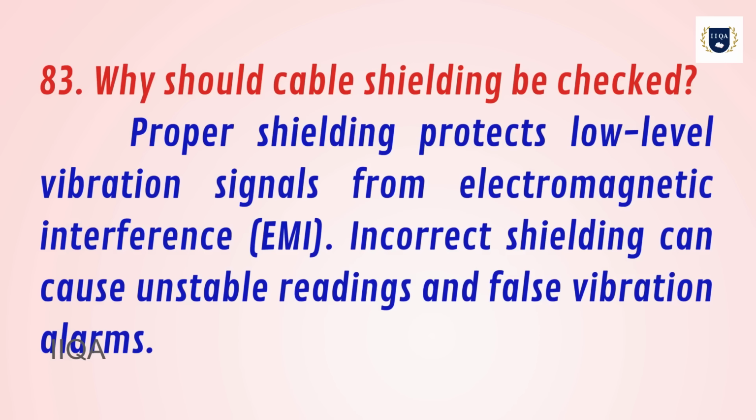83. Why should cable shielding be checked? Proper shielding protects low-level vibration signals from electromagnetic interference, EMI. Incorrect shielding can cause unstable readings and false vibration alarms.